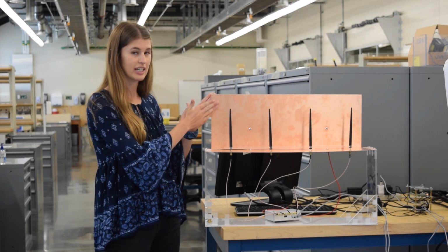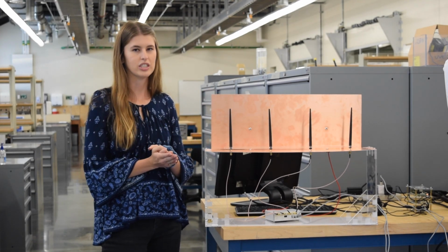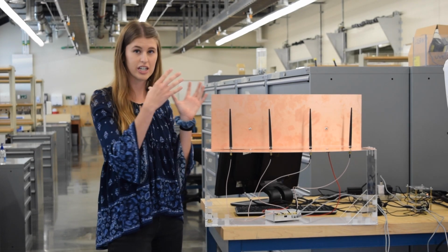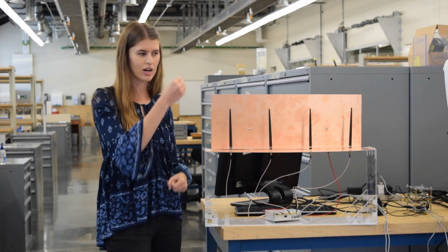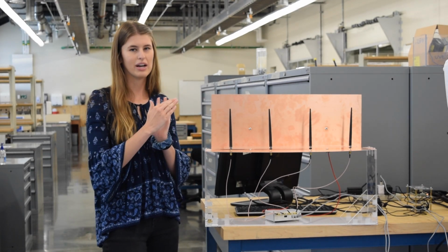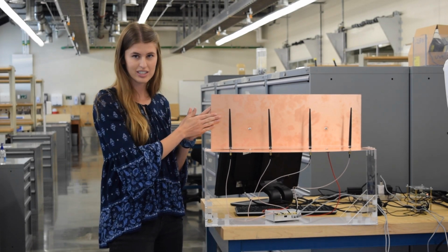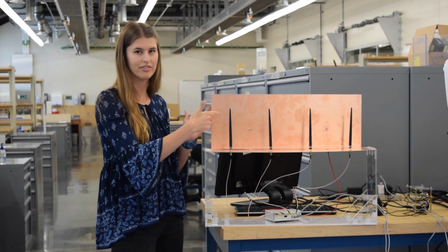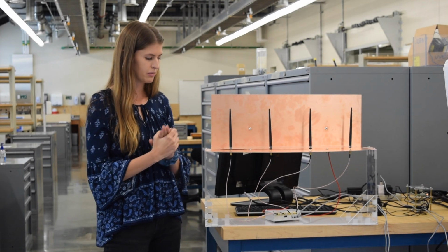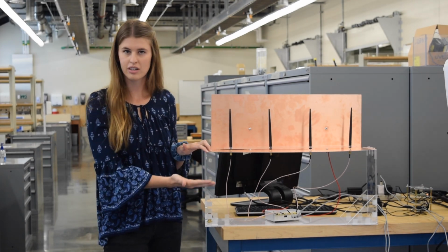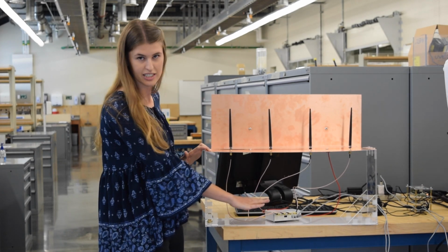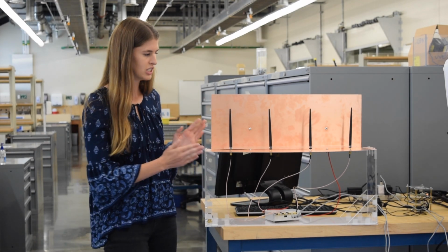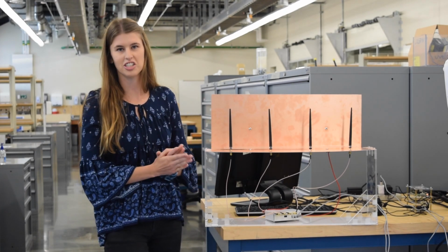And then we also have this second copper sheet, which is another ground plane. This protects so that when the signal comes in, the projector is right behind it. There's a metal rod, and tables have metal, which bounces signal really well. But when you've grounded it, it does not. So this helps when the signal's coming in, it does not bounce back off and hit the antennas again. And then we also have it just about a foot off the ground above the SDR, because this also is causing multipathing and some issues with the signal. So we had to elevate it about a foot above the SDR.